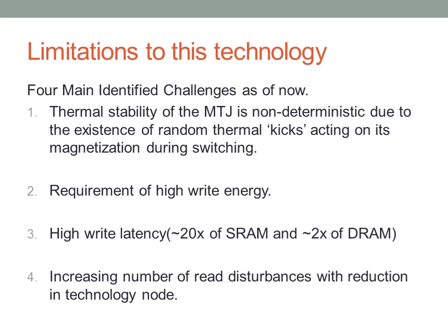The second challenge, as mentioned earlier, is the requirement of the high write energy. The third challenge to this technology is the high write latency of the STT-RAM, which is much higher than that of the SRAM and the DRAM. The fourth challenge has been recently identified, and that is the increasing number of read disturbances with reduction in the technology node. This is basically because the margin between the write current and the read current is decreasing with decreasing technology nodes.